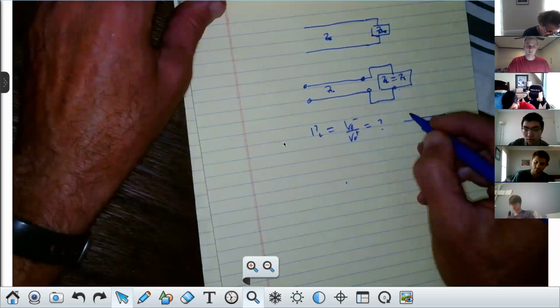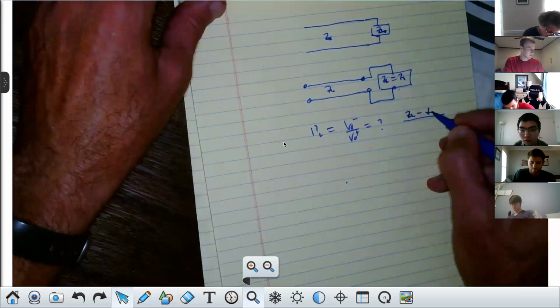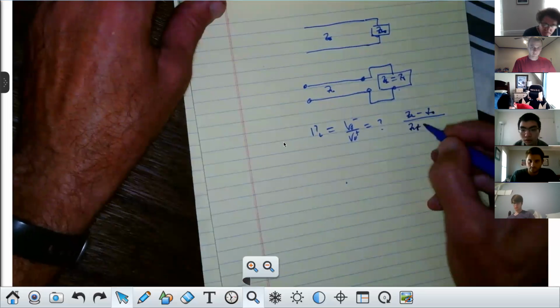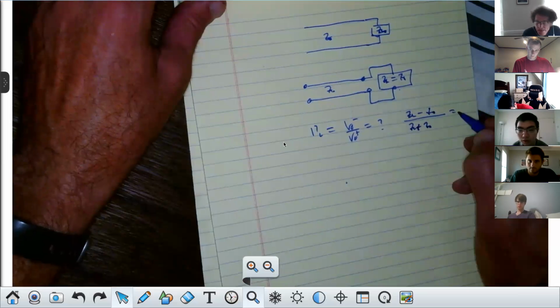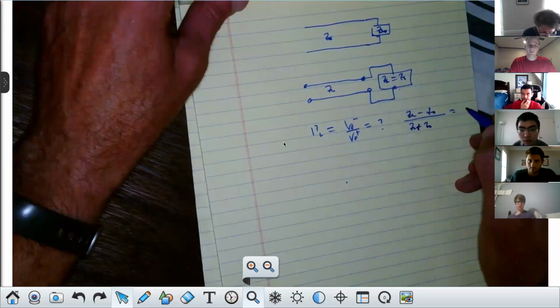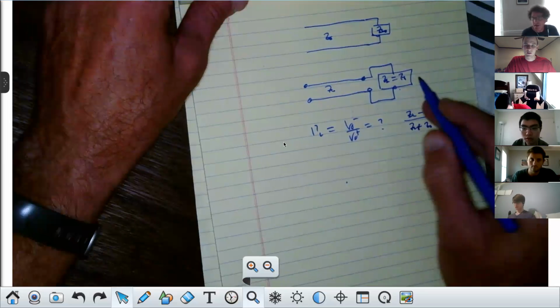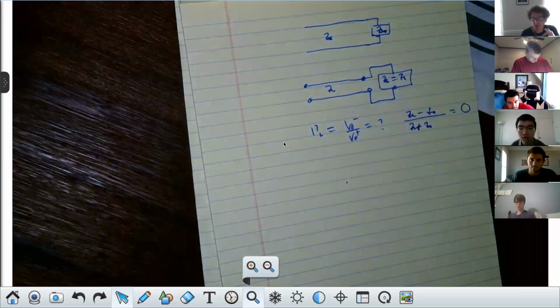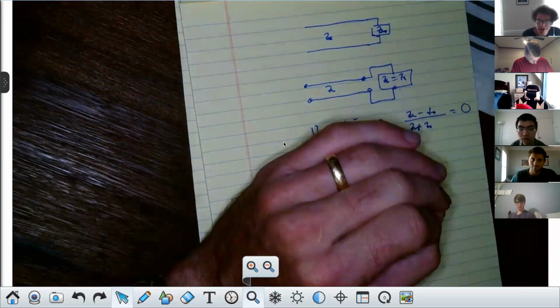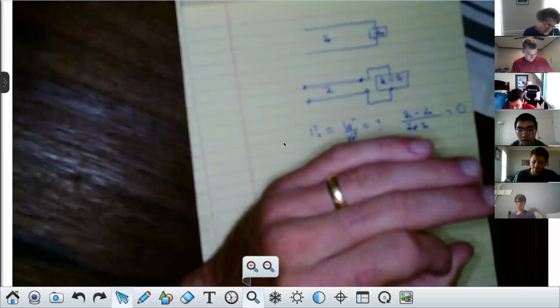It's ZL minus Z naught over ZL plus Z naught, right? And what is that value? That's the point I'm getting at. It's 0, right? If ZL is Z naught, it's 0. Do you agree with me? It means nothing's reflected. That's our goal. Can everybody hear me okay? That is the goal. So how do we do it?